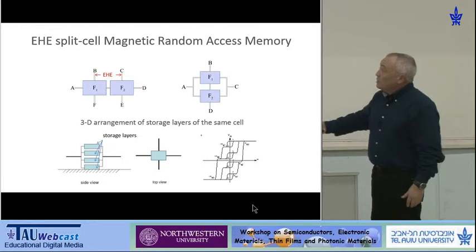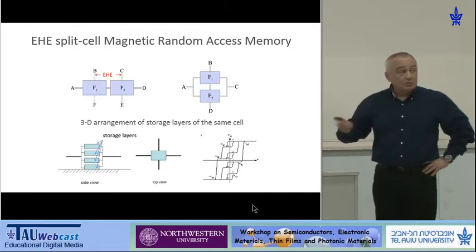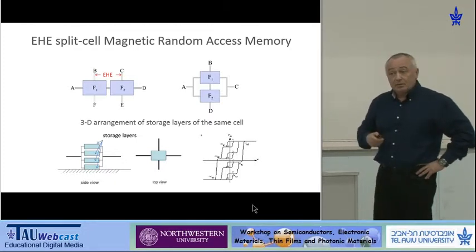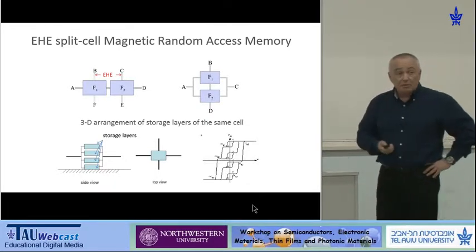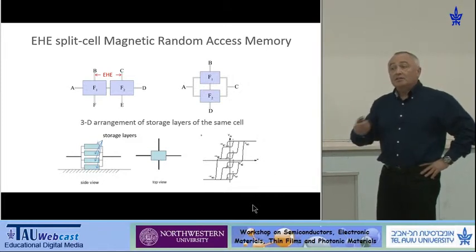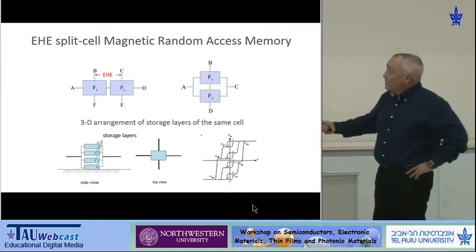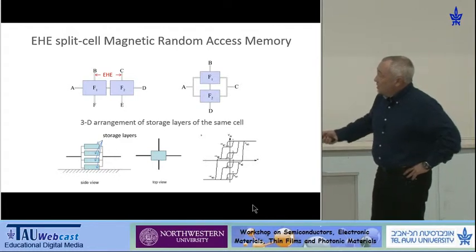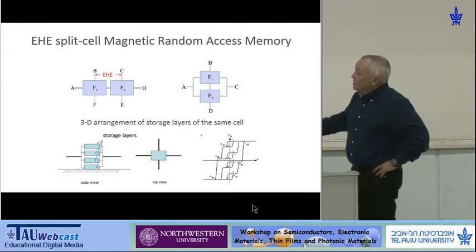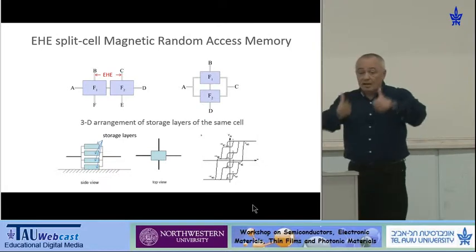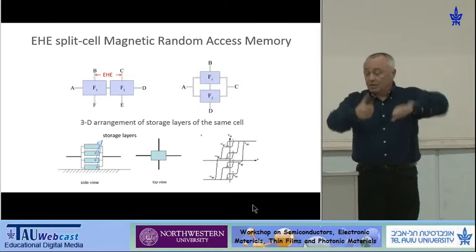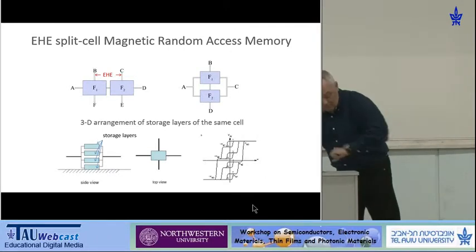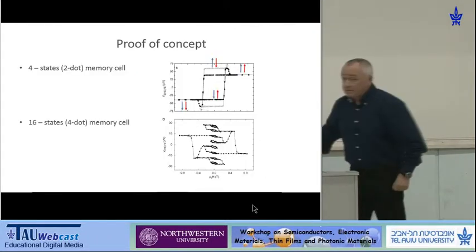Okay? Now what we know to do, and this is due to symmetry of the anisotropic of the Hall effect, we can reduce all the symmetric part, so we can reduce the entire resistance, and we can stay with anti-symmetric part only. And then if we have that, then we get the signal which would correspond either to both parallel up, down, this way, or this way. Okay? So the result would be like this.